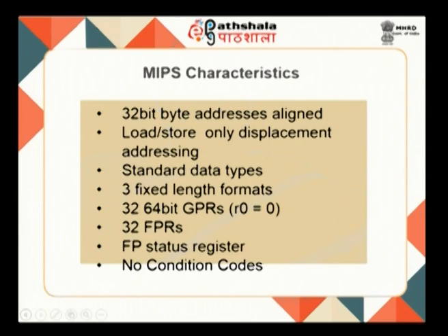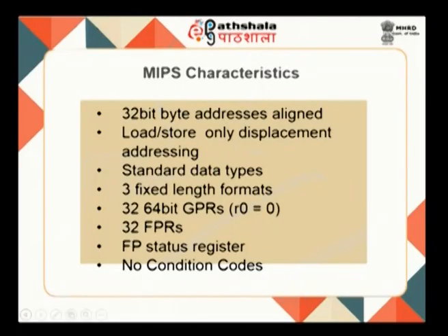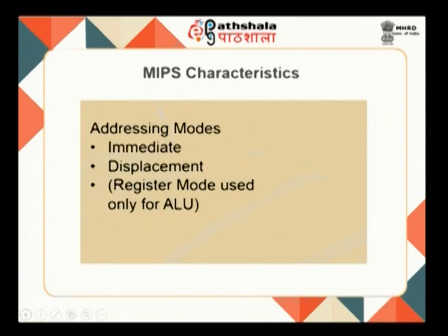You cannot look at any other format. It is a fixed length format, and you have 3 templates which all have fixed lengths, and you have 32 64-bit general purpose registers with register R0 equal to 0. You have 32 floating point registers, you have a floating point status register, and there are no condition codes supported here. The addressing modes that are supported in your MIPS architecture are immediate addressing, displacement addressing.